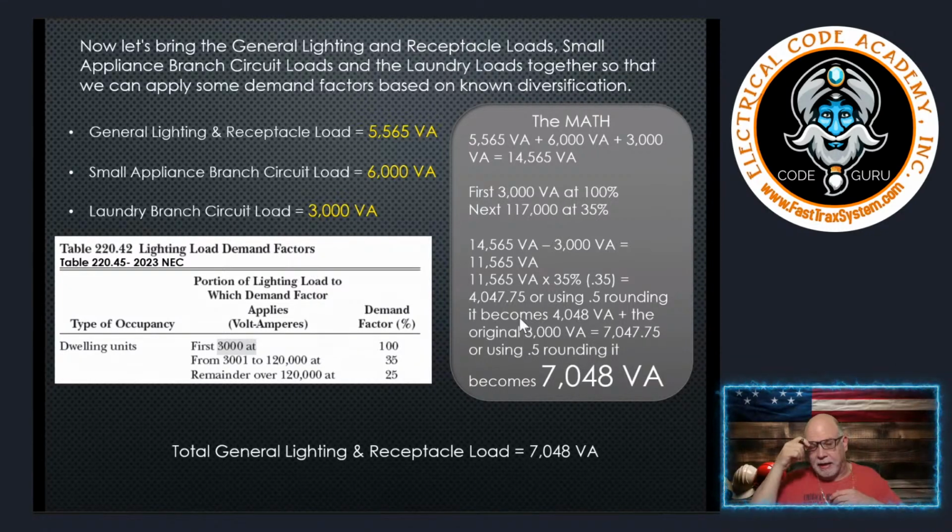Now, here's the first thing I'm going to remind you in this process. That is also neutral loads. We get to apply the same demands that we just did for the neutral as we're doing for the hot. So I recommend, when you're doing a calculation, to save you some time, although we're going to do the neutral quickly at the end here, just write it out in the open column beside it. Keep track of your neutrals out here.